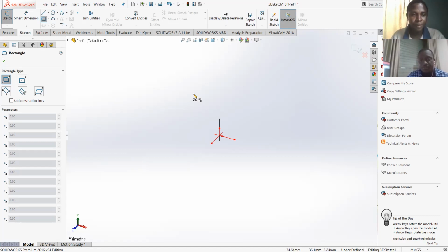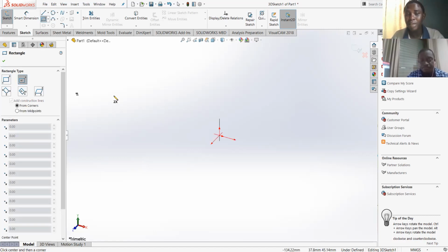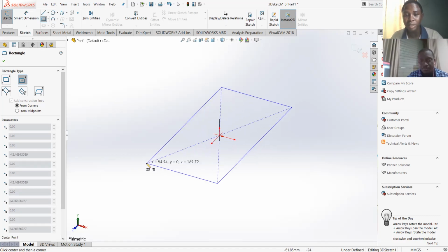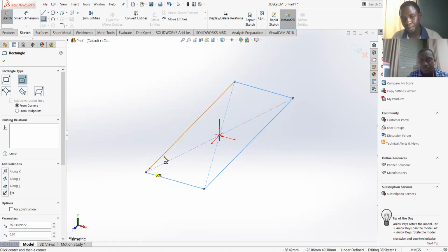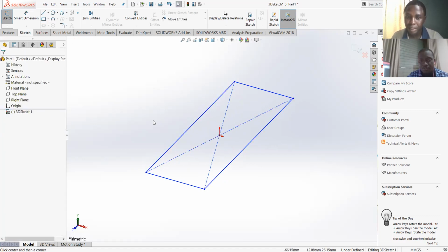The top, okay. So I will take the center point rectangle that I wanted. I create the first point, which is at the origin. This place is now the origin of all the lines, the Y line and the X line. So I'm taking that origin and I'm doing this. Okay, very simple. So I'll begin to introduce some constraints.